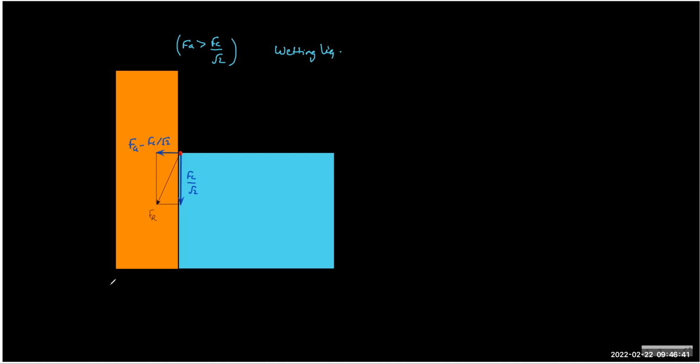Now, what we need to understand is the property of free surface. A free surface is defined as a surface which is always perpendicular to the resultant force, or you can say a surface is said to be free if there is no tangential force. So now the liquid will try to take a new curvature near the wall, which is exactly perpendicular to this line.